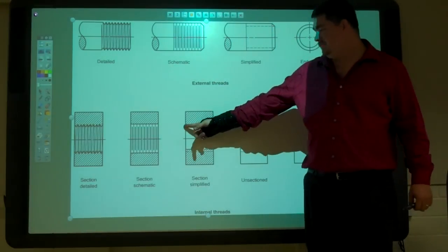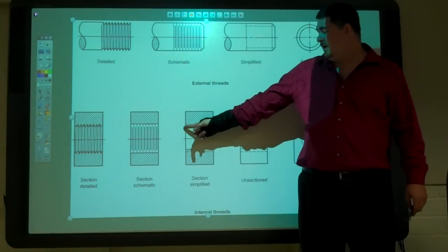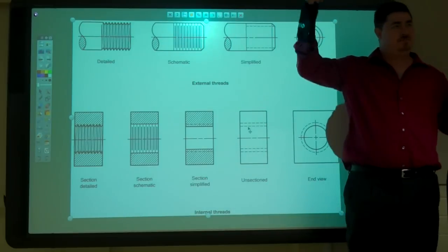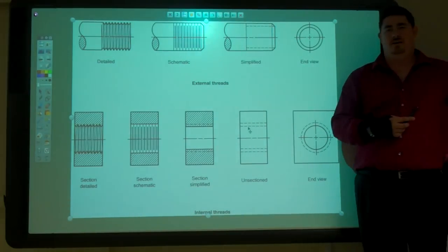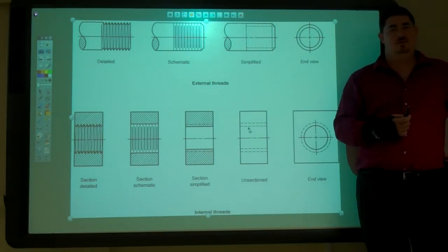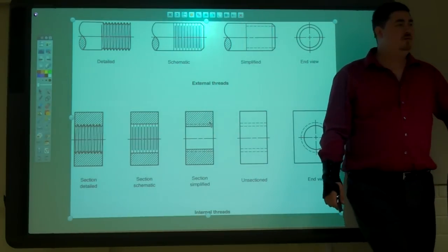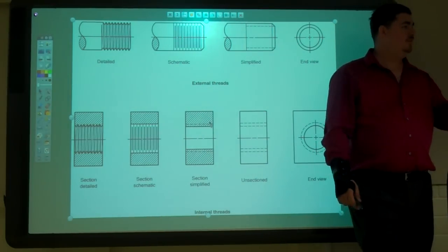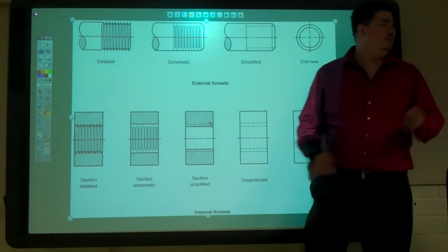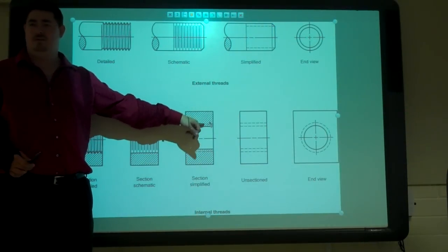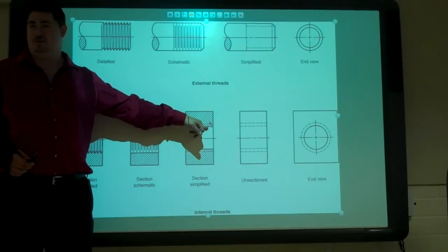When we section it, the minor diameter is our solid top line, so the major diameter becomes our hidden line. Why do we do that? Why don't we stop the hatch at the major diameter? Because you're going through. That's not where it fits level. Yeah, because at the top, there's still stuff coming down below it. But at the minor diameter, there's nothing that goes below that point.